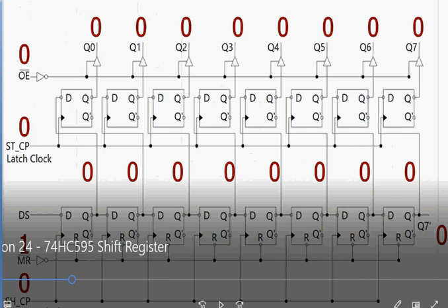How is it possible? Again apply the clock pulse. This bit will be moved from this place to another place, and the data C0 which was present here goes to the next shift register. So in the second shift register you can display the message now. That can be enabled, others need not be enabled. So only in the second 7 segment module you'll be getting the result.